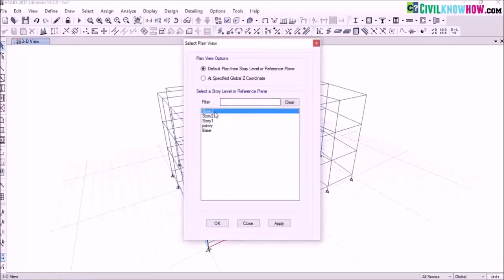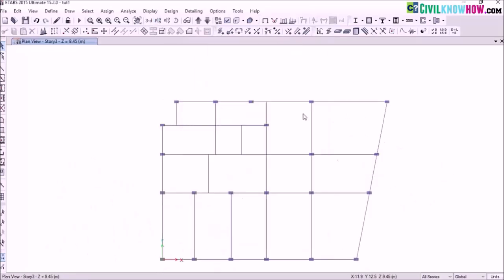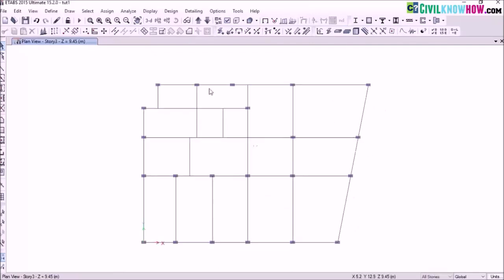And let's go to the plan view. But in my actual plan, the orientation of my columns is not in a single direction, because some of my columns are oriented with respect to the 90 axis, and the columns over here are oriented at an angle actually. So let me first select the columns that I need to orient to 90 degrees.